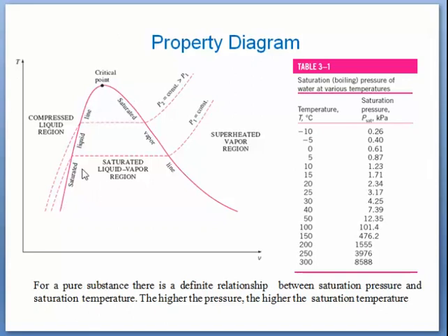And over this diagram, this point is known as critical point, where this saturated liquid line and saturated vapor line join together. You can see here in between, this is saturated liquid vapor region or wet zone, and the meaning of increase in pressure will be that this constant pressure line will shift in upward direction. So we are increasing the pressure, so this line has shifted to this, and finally when we are further increasing it, it will lead to this critical point.